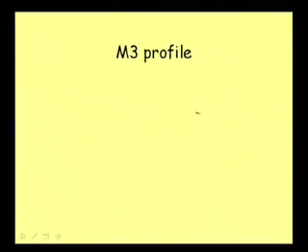then let us see, we are left with one more profile in mild slope, that is the M3 profile. Okay. Now, in the M3 profile, say this is the bed, slope is always mild, SB is less than SC, and of course, it is positive.